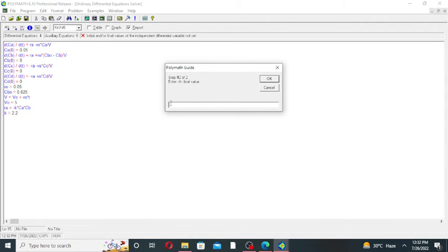Similarly, it will take some time to open and close the valve of the semi-batch reactor when the volume of the reactor becomes full. It will take at least 1 minute to fill the reactor from 5 dm cube to the final volume, and about 4 or 5 minutes for the valves to open or close.